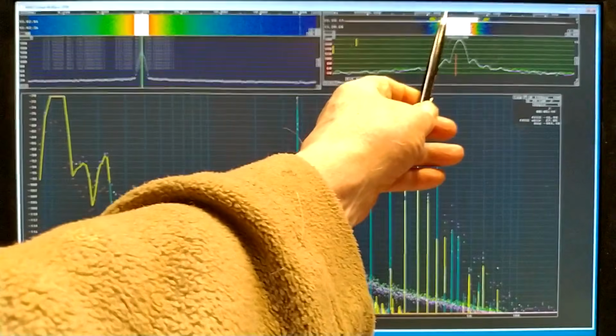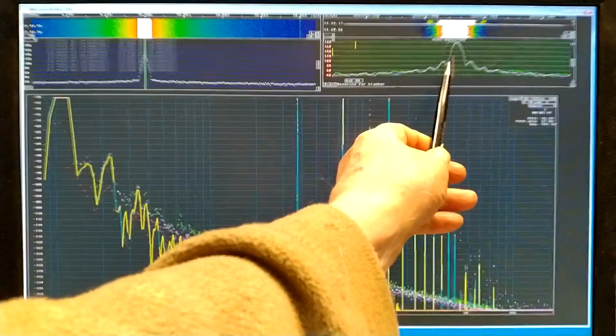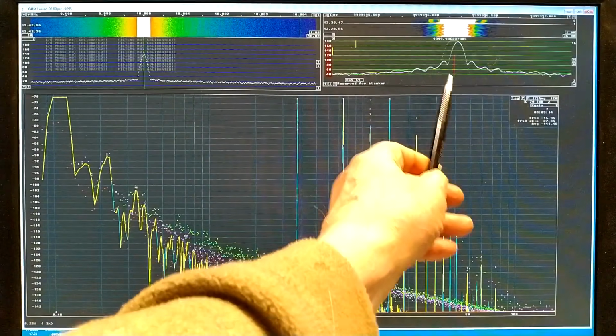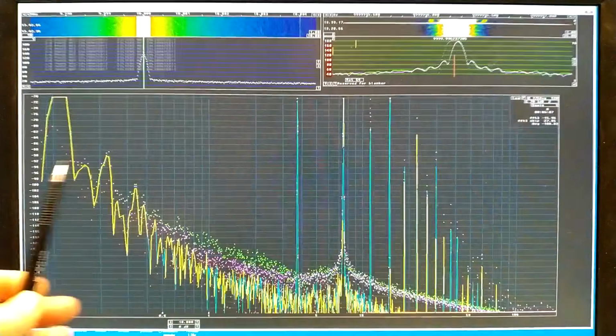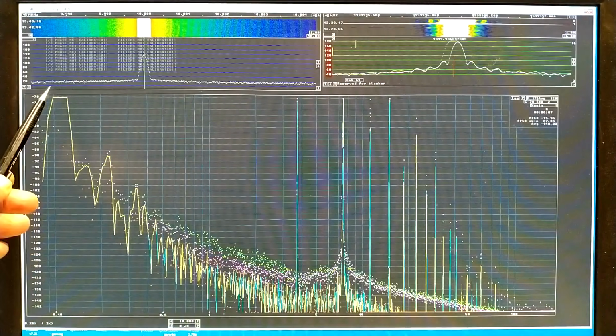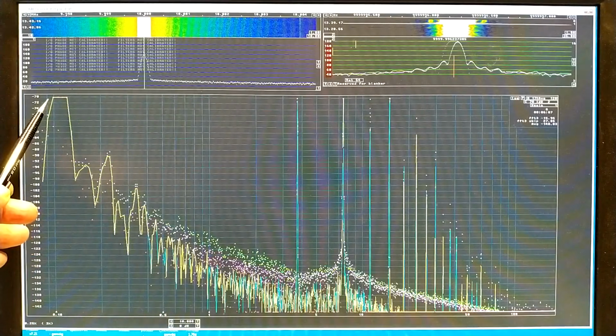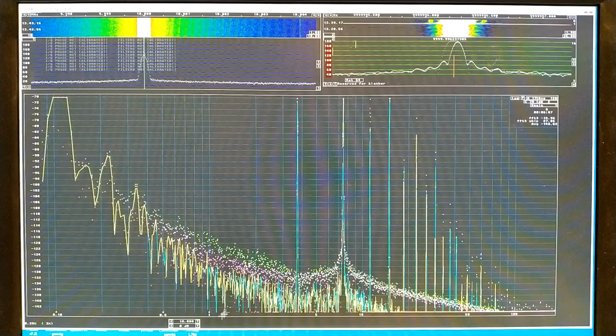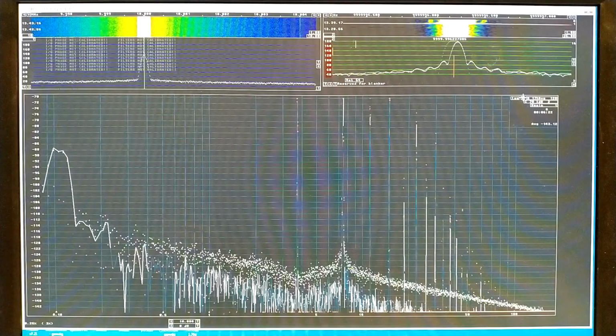These noise sidebands, the fundamental and the overtone, are very strong. You can see they are out of scale also at -70 dBc per Hertz. I can look for the amplitude modulation, and it is also strong,